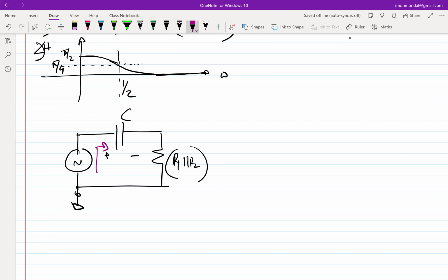Effectively, because the capacitor is giving you almost the entire impedance. So the impedance that the source is seeing is approximately 1 by j omega naught c. So if the source is seeing that much, what will be the current? Basically at very low frequencies, capacitor dominates, because it's in series. Effectively, the impedance is 1 over j omega naught c. So the current will be j omega naught c times Vi,